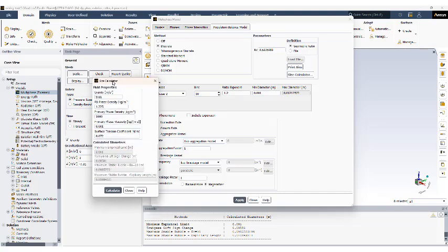And then I click calculate, and it will tell you the minimum empirical limit for the calculated diameter. So I selected that value here, and I also used a value for the maximum diameter somewhat closer to the maximum stable bubble size based on the capillary length. However, it's a bit higher than that. To change the maximum diameter, you can change the number of bins, or alternatively the ratio exponent. If I change the ratio exponent here, for example to 1.4, it's going to automatically change my maximum diameter as well. So I can go back to 1.2, and then we can activate the phenomena.